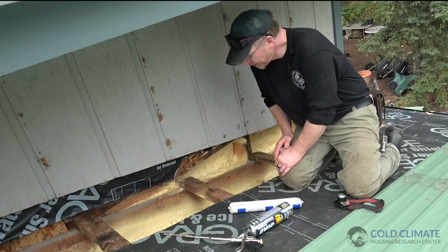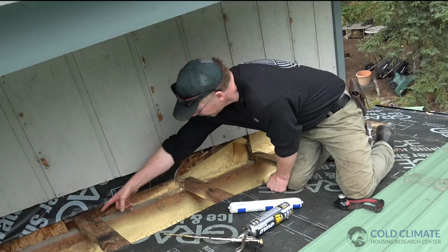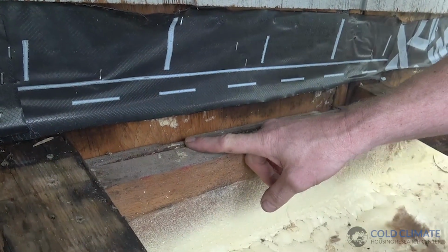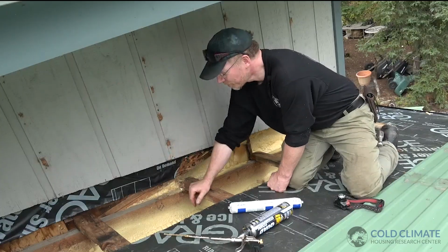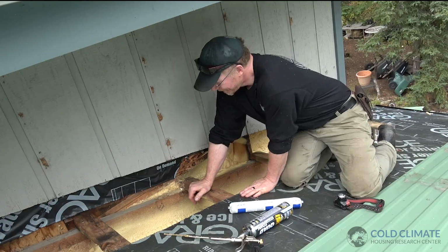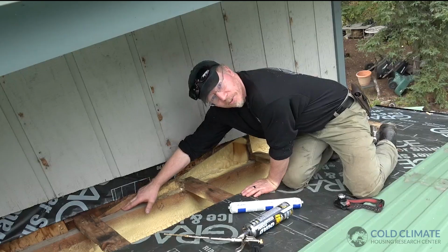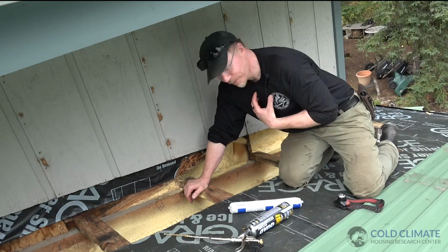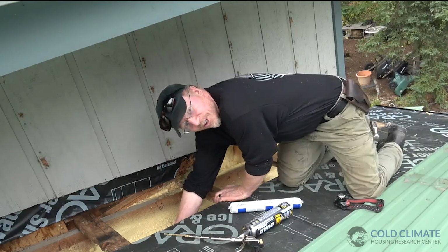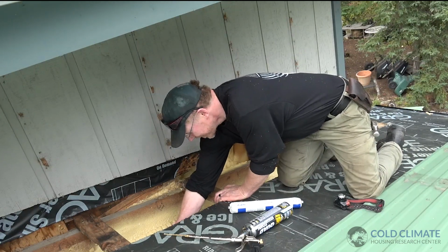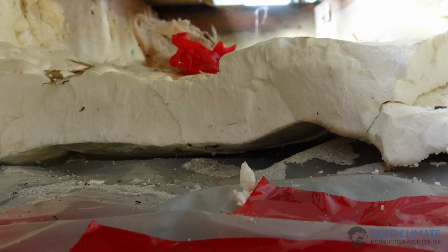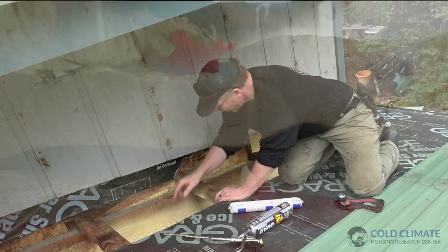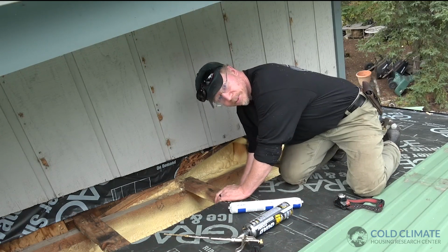The one tricky area is going to be sealing this continuous gap that runs between the old siding and the new wall. That's a continuous airspace up this rafter bay. And I realize the tendency is just to want to seal right here at the top. The problem with that is our primary pressure boundary, the spot that separates our indoor air from our outdoor air, is down below here at the bottom of our foam where our polyethylene sheeting is. So realistically, we need to start our air seal, I feel, down here at the bottom of the rafter.